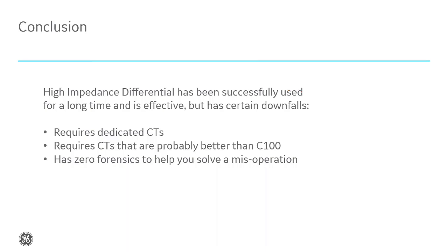And the last thing is you really don't get any forensics around how to solve a mis-op problem. All you know is the current that you've got there. So if you've got a wiring problem, it's very difficult to figure out which one of those CTs is wired backwards.